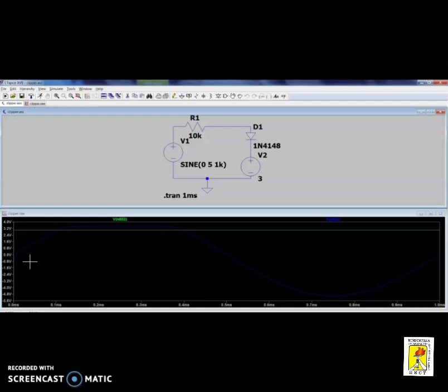The biased clipper consists of a diode with a battery of a few volts. This voltage should be less than the input voltage. A portion of each positive half cycle will be clipped. And if we change the bias voltage to negative, accordingly the voltage will get removed from the main supply voltage.